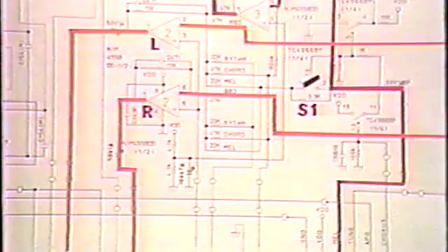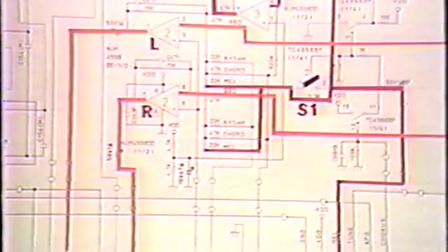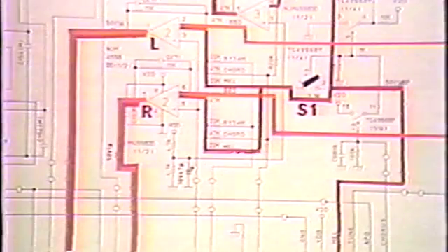S1 is off at this time, but the sounds which are not delayed pass through the 3.3 kilo-ohm resistor to lower the sound level, enter the mixer, and can be heard from the center. Next, we will explain how to create accompaniments.